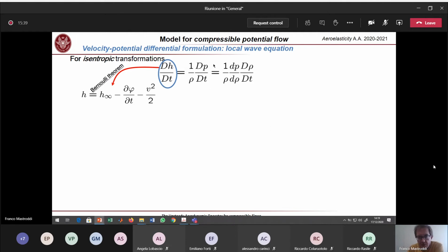So here in this equality, we have assumed that the pressure is a function only of the density because of the state space equation. Okay, so we are assuming a special state space equation connecting a scalar quantity like the density and the scalar quantity as the pressure as a unique relationship. So we have this relationship as given by the chain rule, and the derivative of the density with respect to the time can be expressed by using the continuity equation.